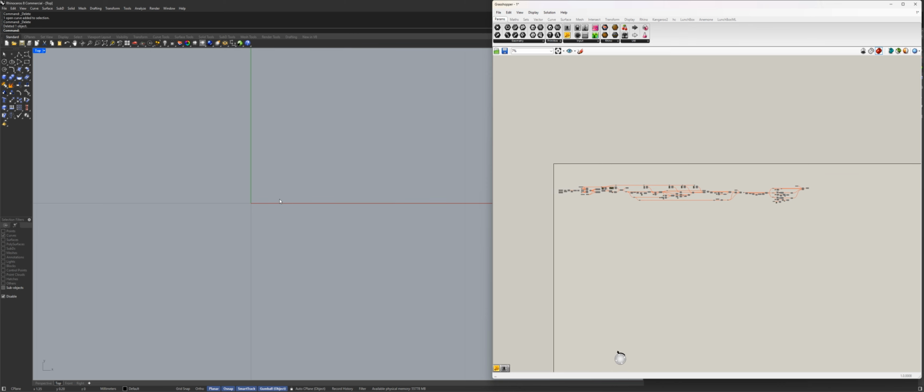Next I will scroll out, because if you remember, we worked with very tiny sizes. Our pattern is normalized for reasons. So for now, we'll just scroll back and I will construct a curve. To do that, I will use this tool in Rhino, called control point curve, and just construct a curve through a few points, for example, here. Then I will click enter, and as you can see, I have myself a curve.